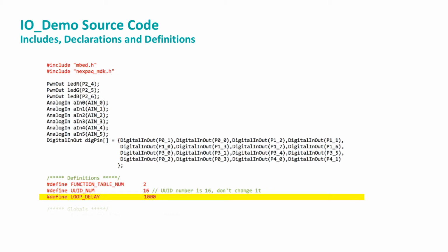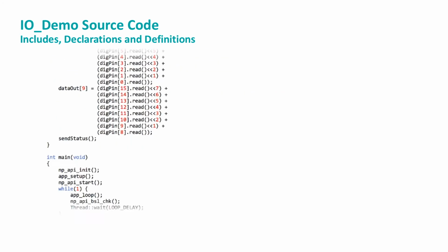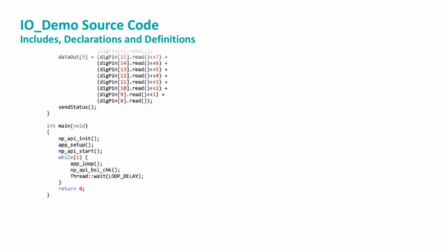Now we've configured all the pins for the device and covered the constants needed by the program, let's drop down to the bottom of the file and take a look at the main function. Every C program must have exactly one function named main. That's the function that takes control immediately after the system is reset. In an embedded system, the main function never returns. It simply loops until the system is reset or turned off.